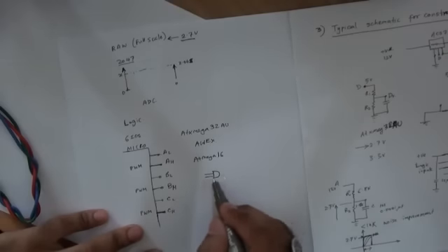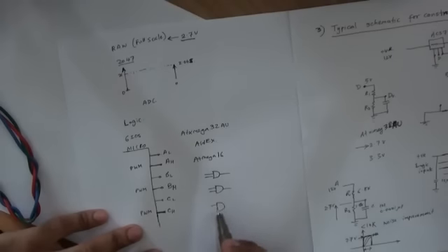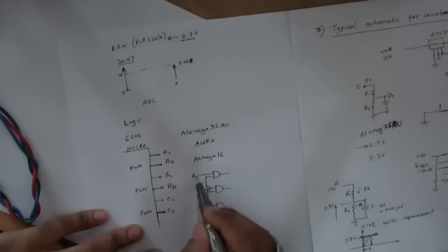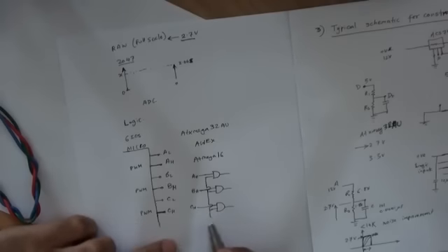So for example, if you had 3 AND gates out of a quad package, you could wire them as such. You could have phase A, logic AH, BH and CH being hooked up there, and the third common one is your PWM.